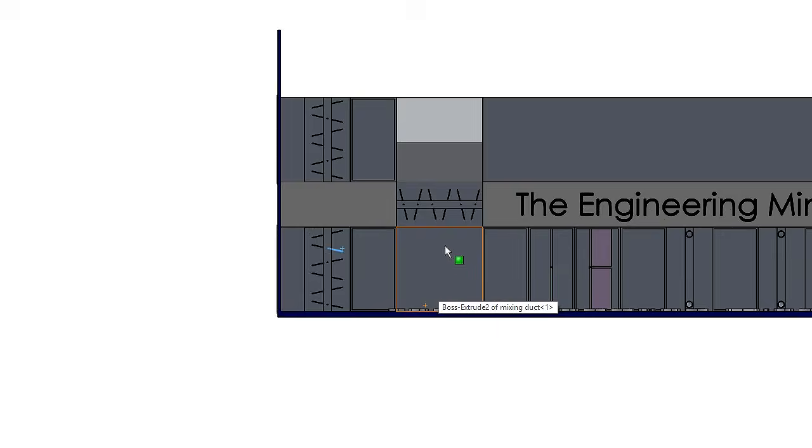If this is 60%, then this is 40%, so that's going to allow 40% of the air going in to have already been around the office, and 60% of the air coming in is fresh air. So that's coming in, and they're mixing here. That's coming in, and that's going this way. So the cold air and the warm return air is mixing here, and then it's being pushed off and out into the building.